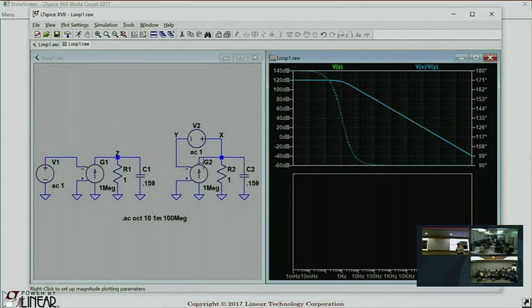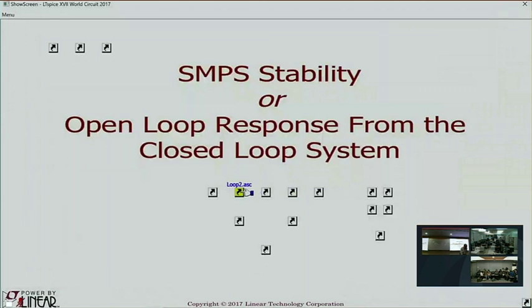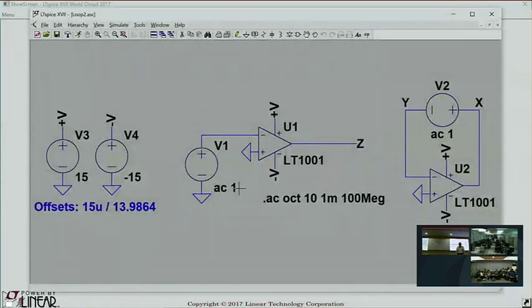Say you don't have a circuit with a transfer function nominally like an op-amp. What if instead you actually have an op-amp? The direct method will not work, because the op-amp has an offset voltage. If you take that offset voltage and multiply it by the DC gain, you have a number which is bigger than the supply voltage. So the output is simply pegged at one rail or the other.